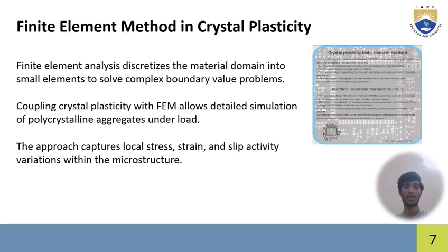Finite element method in crystal plasticity. The finite element method, FEM, divides a complex material domain into smaller elements, allowing detailed analysis of stress and strains. When combined with crystal plasticity, FEM can simulate how each grain in a polycrystalline material behaves under load. This coupling helps capture local variations in stress, strain, and slip, providing a micro level understanding of deformation that traditional models cannot achieve.